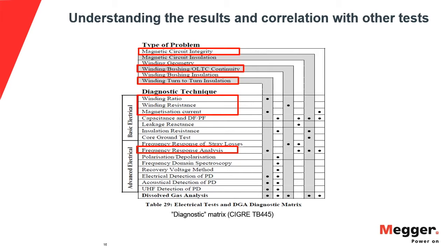And finally, the frequency response analysis, what is normally called SFRA. More specifically, if we look at the inductive interwinding test, we can get a very good approximation of the ratio using the flat magnitude response in the lower frequencies, less than 60 Hertz.